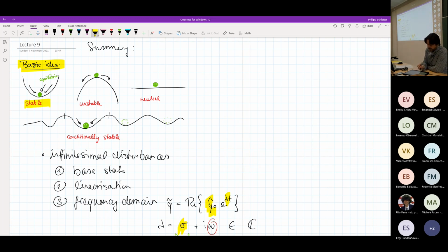We distinguish stable from unstable flows in the sense that in a stable flow, whenever you have a flow state, which may be the Poiseuille profile, a certain velocity profile, and you start to disturb this flow, so you hit the flow a little bit, there's a little bit of noise, maybe some vibrations, maybe some surface roughness, the flow is then called stable if the flow goes back to its original state. On the other hand, the flow would be unstable when you disturb the flow a little bit, and then it would go somewhere completely different in phase space.